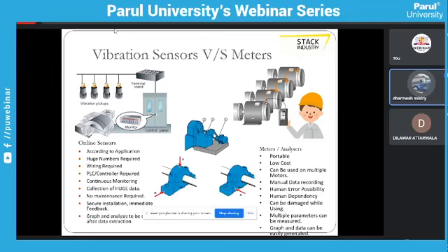So in a continuously running plant, they monitor all the data of all the vibration sensors, and they set a limit. For example, if the standard is 4 mm per second and the motor has crossed 5 mm per second, they will create an alarm at 5 mm per second, so people will know that motor number 990 has some problem. Whenever maintenance is scheduled, they will clean the motor, or check the motor, or replace it and send the old motor for repair. This is called preventive maintenance.